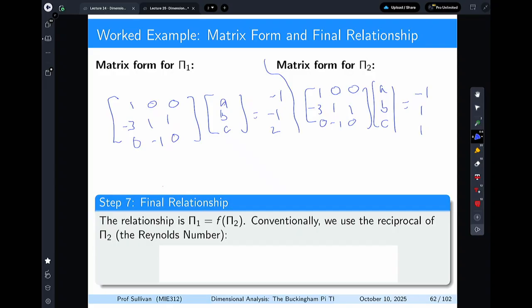And any time that I have something that says inverse Reynolds number, I'm going to flip it. And again, you're allowed to do this because you are not doing quantitative math here. You're not doing any type of calculation. You're just showing that there is a relationship between one set of variables and another. So even though you get an inverse relationship for Reynolds number, you can just say C sub d is a function of Reynolds number.